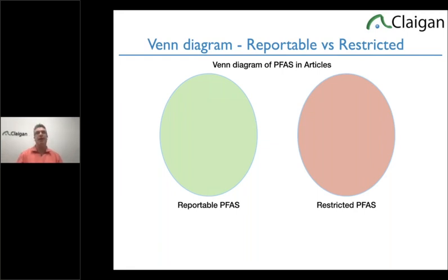The funny thing is, if you actually go over what the hazard is, fluoropolymers are about the safest thing you can possibly imagine. There is a potential unintentional contaminant that is dangerous in high concentrations, but not at the level inside PTFE. It's absolutely harmless in there. If you're going to ban that, you might as well ban laundry detergent. The reason PFOA is dangerous in high concentrations, like downstream from a plant or in your makeup, is because it's a surfactant. It's a very simple property. Surfactants make oil and water mix better.